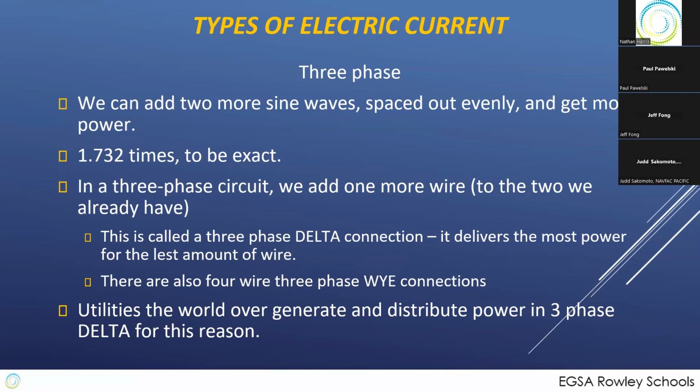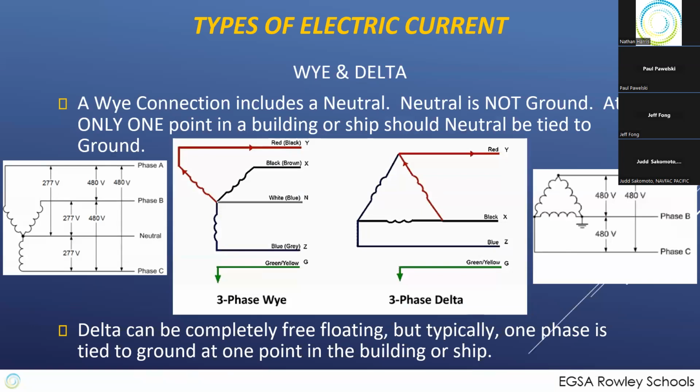And so you're going to have to be working from that delta connection to everything else that you're trying to do on the site if you're trying to do both your own power supply and power from the grid. So what's the difference then between the Y and the delta? Well, the main difference is having a neutral wire.